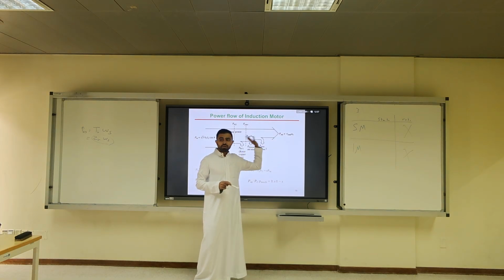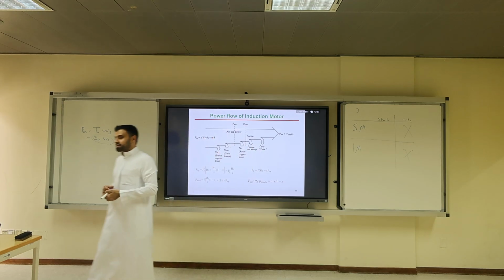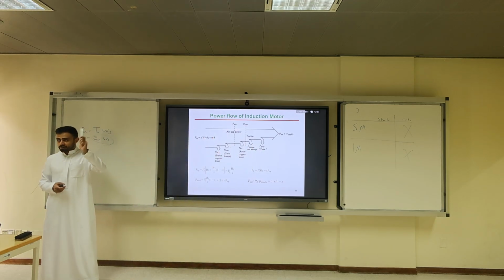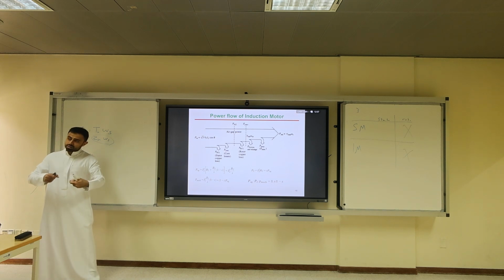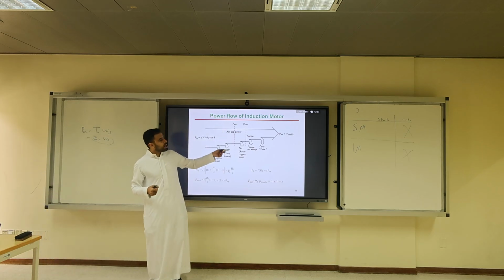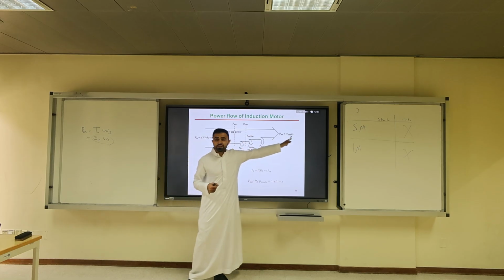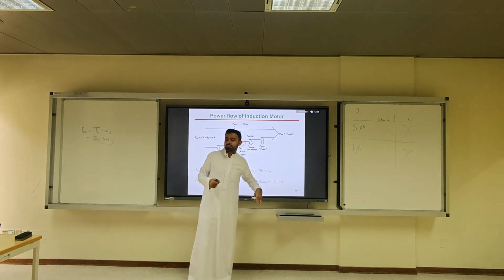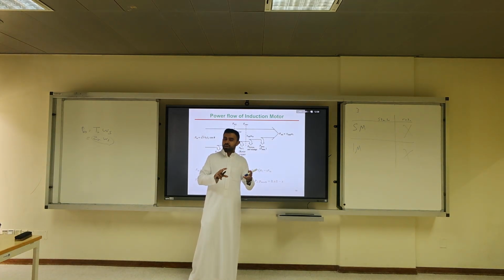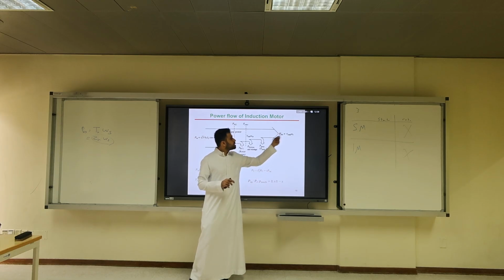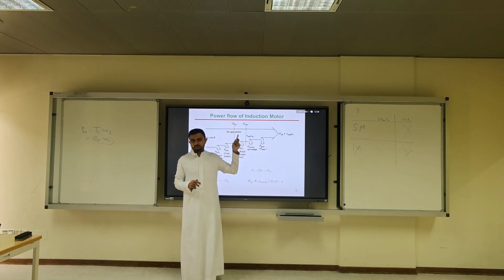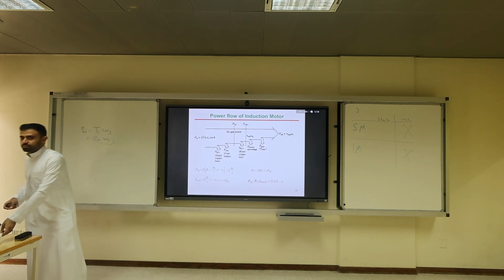I always bring the example of a winch. In the winch that pulls, there is a torque on the other side of the car that you're connecting. They have to be greater than or equal. On the winch it has to be greater than, so the air gap torque, the torque induced, has to be larger than the shaft torque. Shaft torque has to be either equal or below. Otherwise, the motor would not spin. So torque load is always less than induced for the case of the motor. For the case of the generator, it's the opposite.